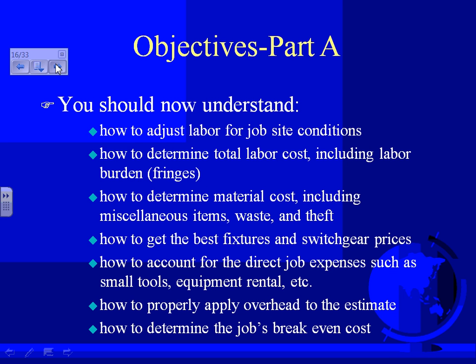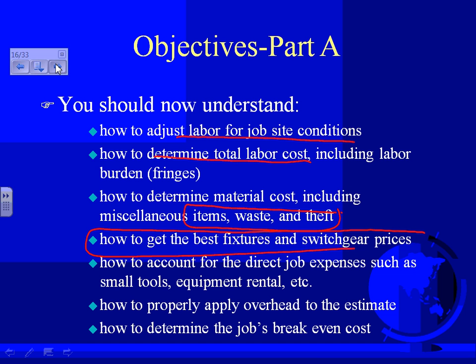Any question, guys? I don't want to go to B today. Any question? So do we know now how to adjust the labor hours based on the condition, how to adjust our labor cost, material cost including miscellaneous waste and theft, and so forth. Switch gear, quotes, very, very important. Quotes, how to get your quotes and plug them in, and account for direct job costs, extra things that you have to account for, and how to apply your overhead.